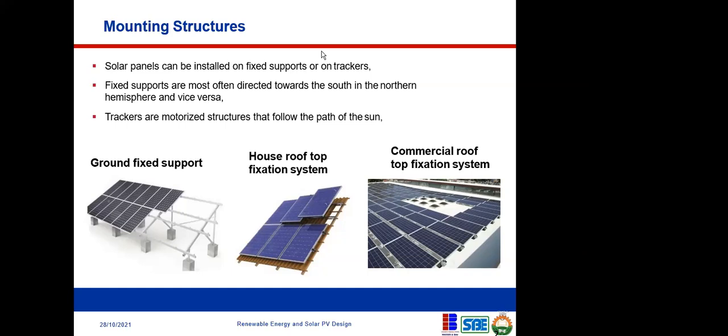I think in the next slide I have a diagram to illustrate that, to make it clear to every one of us. But just as an introduction, or as a rule of thumb: if the location of your installation is in the northern hemisphere, your solar system should face the southern part of the hemisphere, of the equator. If you're in the southern hemisphere, your solar system should face the northern part of the equator. We'll come to that. Don't worry, there's a diagram that helps us to understand it.